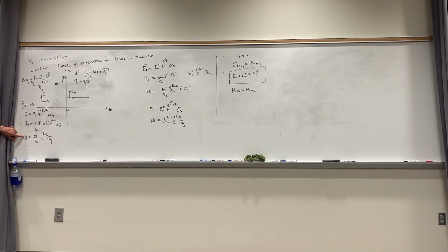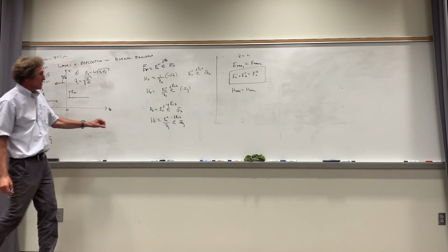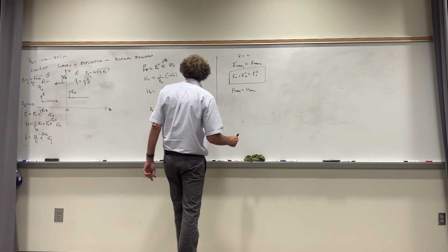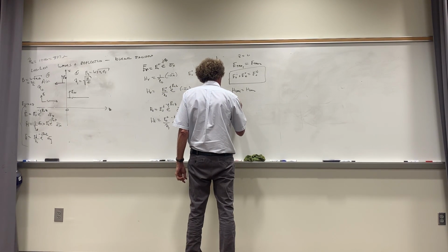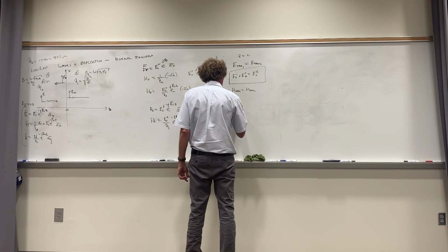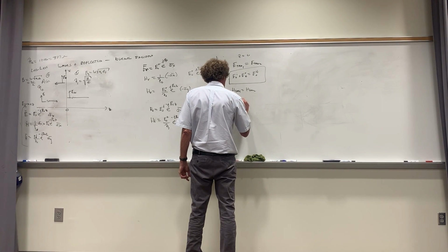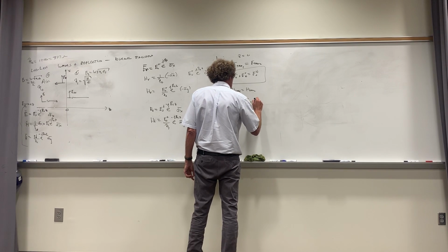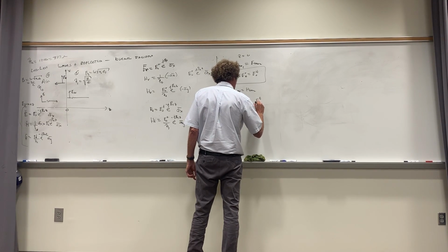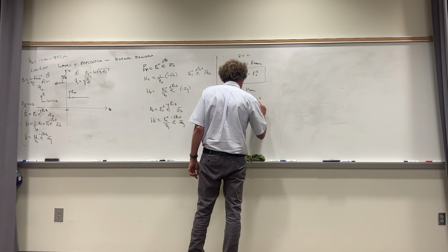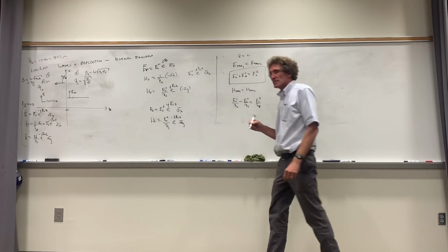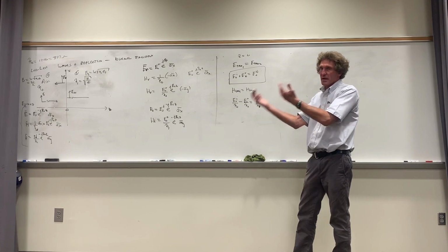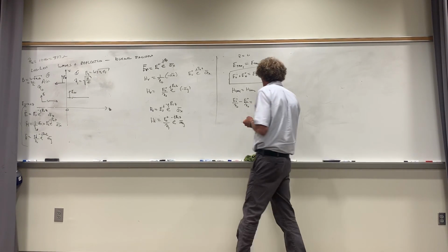And we have this right here, which is minus E naught reflected. So we're going to have E naught incident over eta 0 minus E naught reflected over eta 0 is equal to E naught transmitted over eta 1. And you don't have to put the AYs there. Did y'all see that, class? That's the H field on one side is equal to the H field on the other side. You'll notice that negative sign.